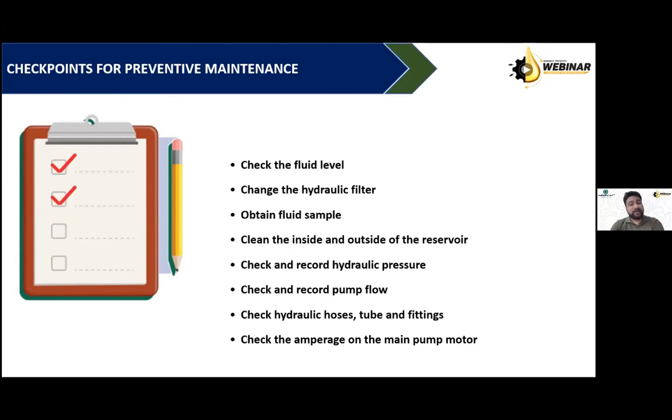Hydraulic hoses are again consumables. They don't last as long as life. So they would be a consumable. And if hydraulic hoses are failing, they have leakages that can lead to plant level accidents, because hydraulic systems work at a pressure which is much, much above a pressure which can actually punch a hole in a human body. So a hydraulic hose failing with your people or manpower working around that hydraulic system is a really very dangerous